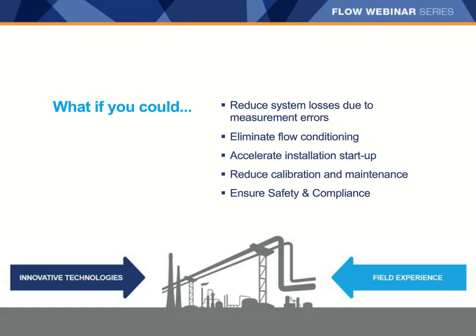You'll no longer be subject to additional errors and uncertainty associated with the ancillary pressure and temperature measurements that were needed with other technologies in order to correct for the changing conditions and how those conditions cause the gas to expand and contract. You will enjoy quicker and simpler installation and startup of the metering runs that will then require little or no ongoing maintenance after they're started. And you'll find it easier to meet compliance requirements with equipment that is extremely reliable and that comes with predictive diagnostics and substantial data and audit trail recording capabilities.